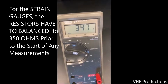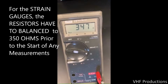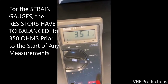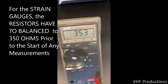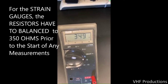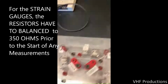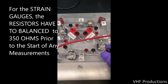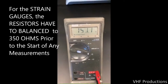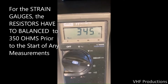We will demonstrate here how to tune the circuit to have all the sides be 350 ohms. And then we will show that the output of the circuit has 0 volts or very close to 0 volts when we start, prior to straining the strain gauge itself, which will be input into the circuit in place of one of these potentiometers. Once we've set up the Wheatstone Bridge, we can now demonstrate how the input of a strain gauge on one side of the Wheatstone Bridge can produce an output voltage.